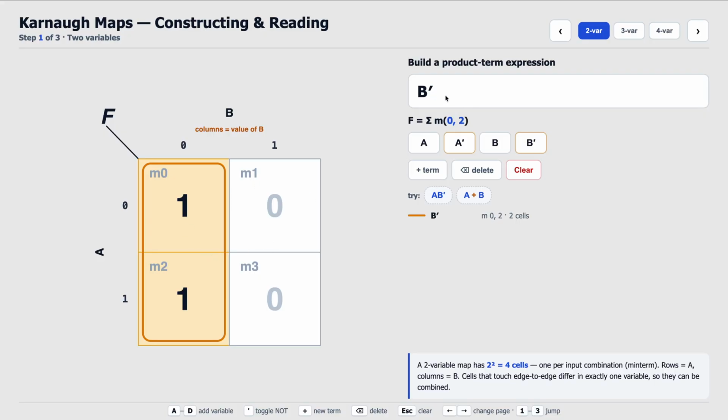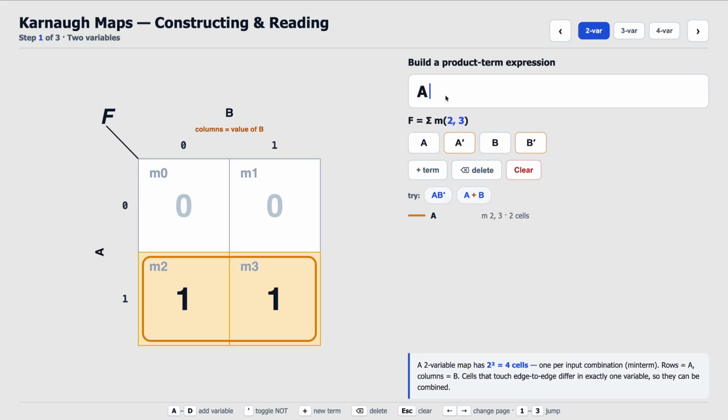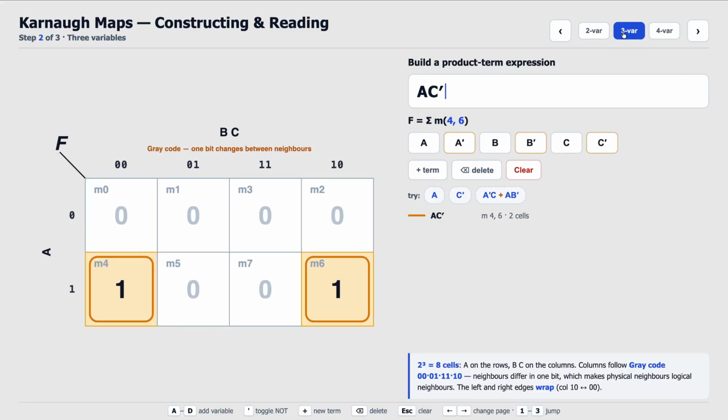You can also represent intersections. So if I did, for example, A, B bar, that's the intersection where A is equal to 1 and B is equal to 0. Just that square. All right, so that gives you the basic idea of how you represent a Boolean function with a Karnaugh map. Let's make this now a little bit bigger of a Karnaugh map.